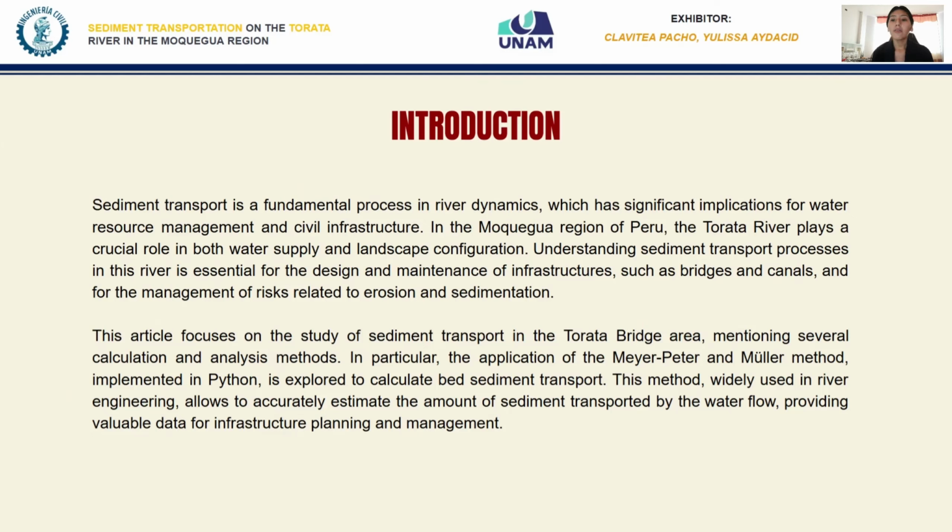This article focuses on the study of sediment transport in the Torata area. Several calculation and analysis methods are explored, in particular the application of the Meyer-Peter and Müller method implemented in Python to calculate bed sediment transport. This method, widely used in river engineering, allows an accurate estimate of the amount of sediment transported by the water flow, providing valuable data for infrastructure planning and management.